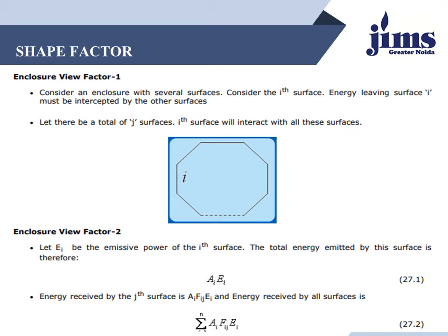In order to compute the shape factor for a certain geometric arrangement for which shape factors or equations are not available, the concept of shape factor as fraction of intercepted energy and the reciprocity theorem can be used. The shape factor for these geometries can be derived in terms of known shape factors of other geometries. The interrelation between various shape factors is called shape factor algebra.